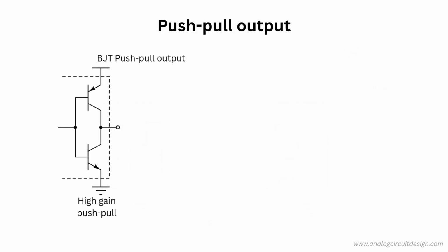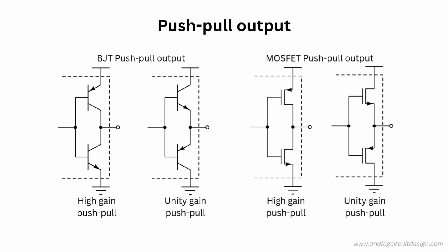In push-pull configuration, both push current transistor and pull current transistor are present. We have shown here some common push-pull stages. Push-pull outputs show significantly better rise and fall time due to unlimited supply of current. Please note that two push-pull output stages should not be connected together.